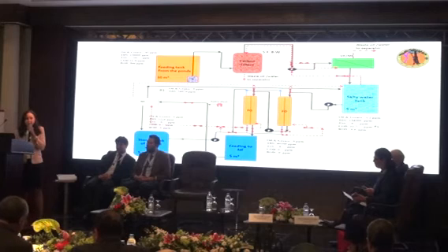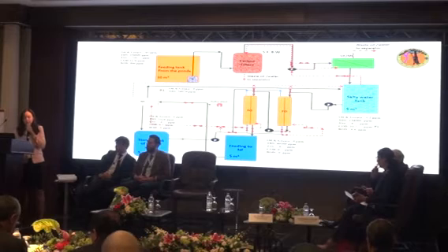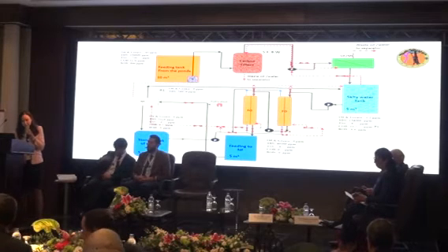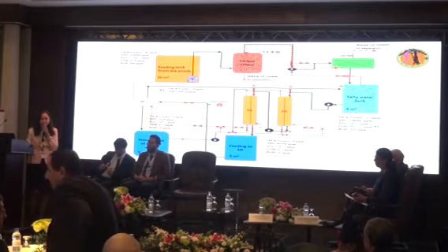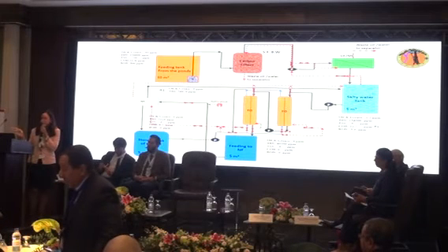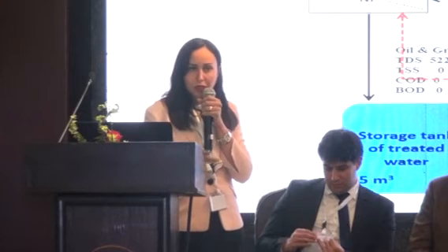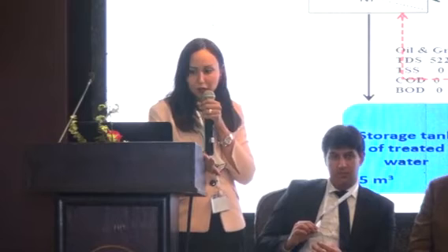Also for the TDS, you decrease it from 130,000 ppm to 5,000 ppm, which can be used in any other facility, or you can re-inject it again to the wellheads. And as I said, the COD and BOD are decreased from 1,900 down to 0 ppm respectively.